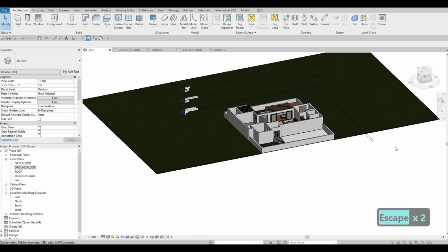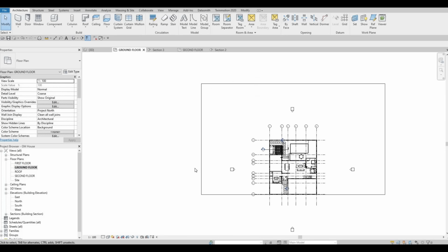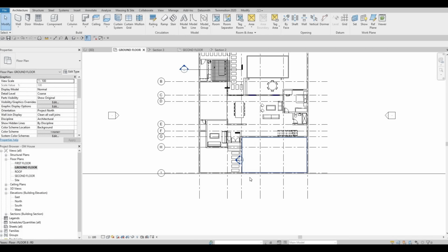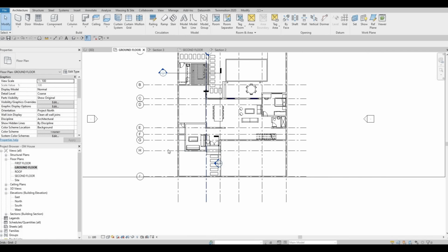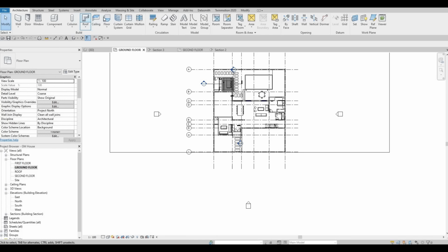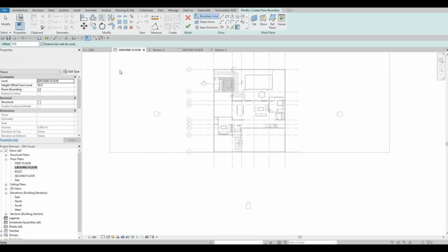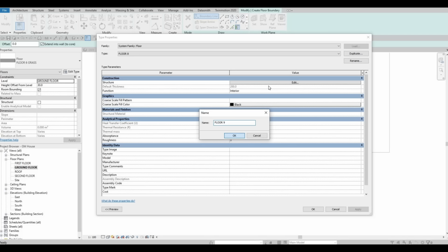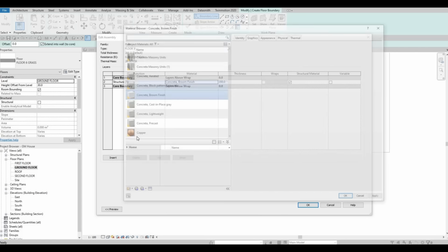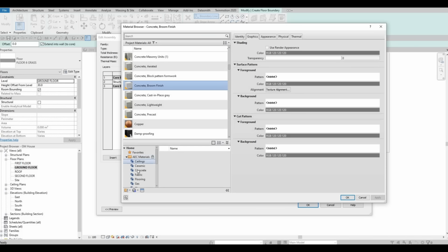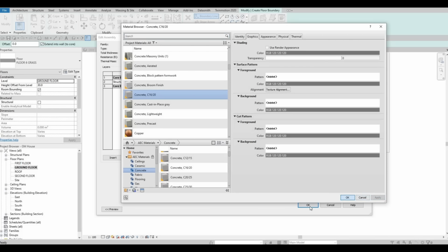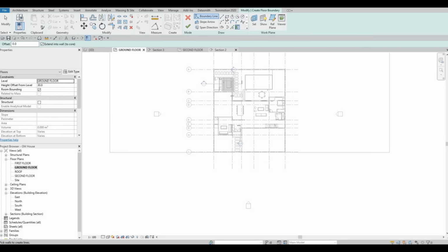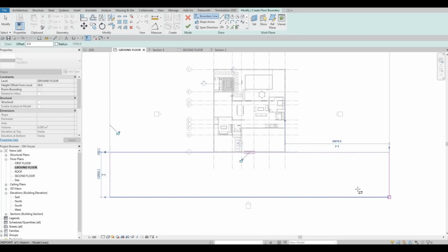We're just going to create the road first, and then let's do something for the gate. So I'm just going to click on floor again. We're going to change this to 8, duplicate on that so that it's 9, edit, let's select concrete, one of this one, press OK, and then just go and create something like this.